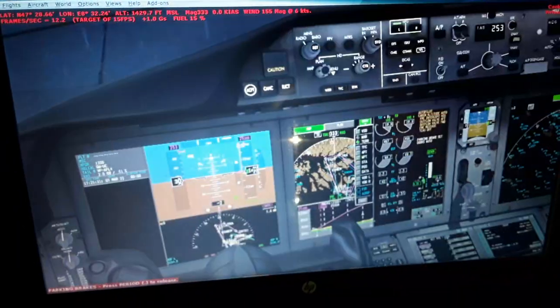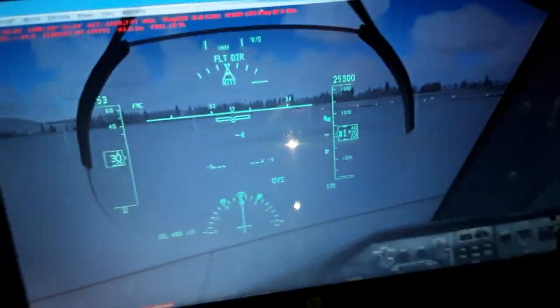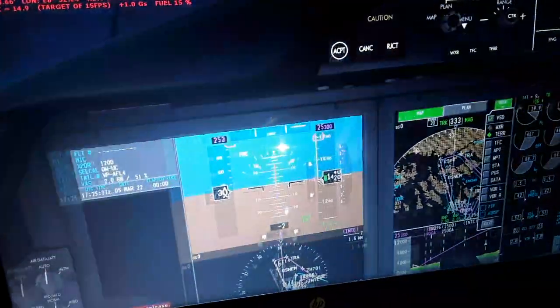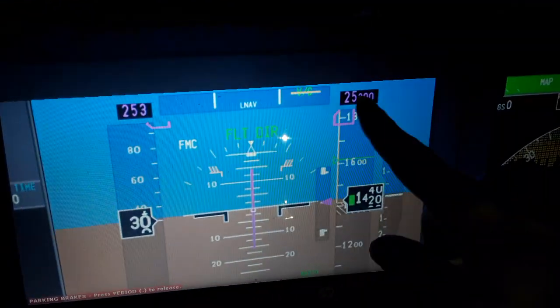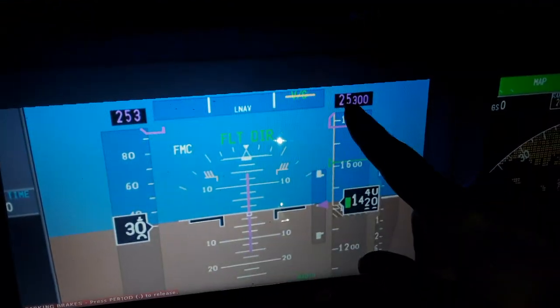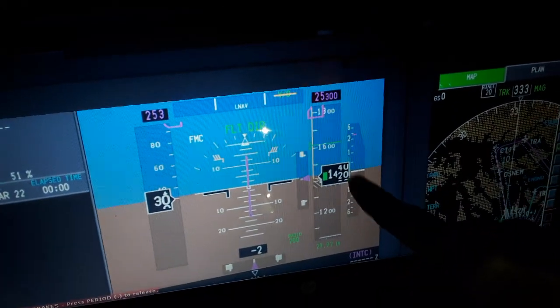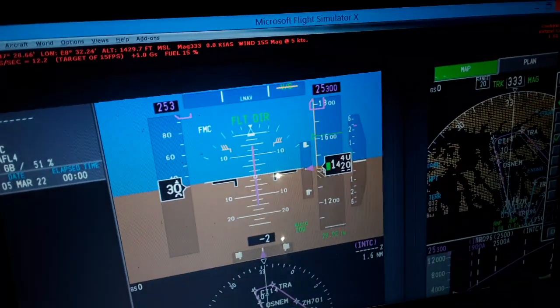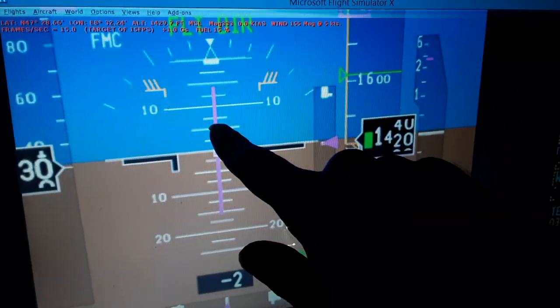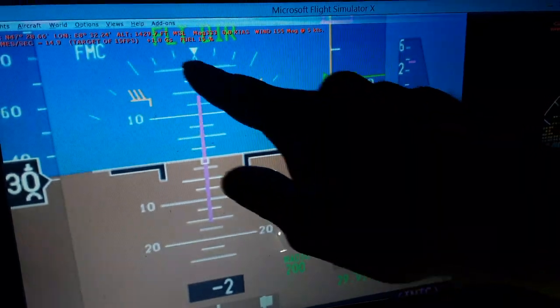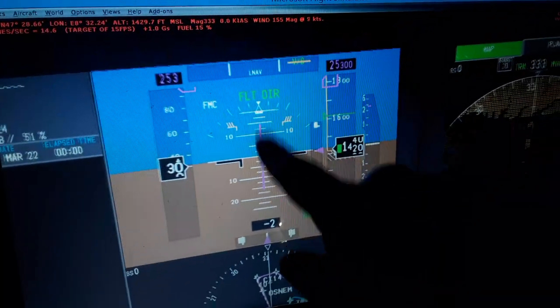So now the autopilot flight director system panel will display here in the head-up display all the information, same like in the primary flight display. You see the airspeed and the altitude change to the target airspeed, target altitude with purple. Airspeed indicated, barometric altitude, the vertical rate of climb or descent of the aircraft, 10,000 feet per minute, the pitch ladder 2.5, 5, 7.5, 10 degrees, 12.5, 15, 17.5, 20 for pitch up or pitch down.